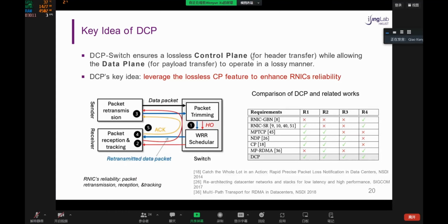I see. Yeah, I think that makes sense, because if you try to implement NDP or CP in hardware, you are spending too much effort trying to improve an existing solution instead of proposing your own design. We have to revisit RDMA's unique architecture and introduce some new necessary modules, for example, the retransmission entry, and improve the data path efficiency.